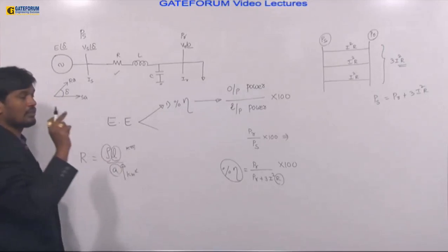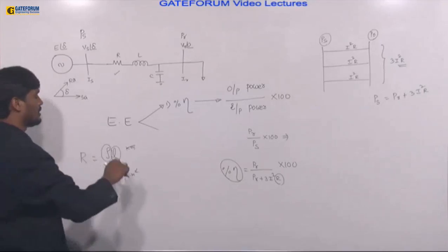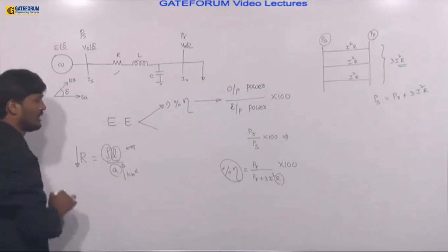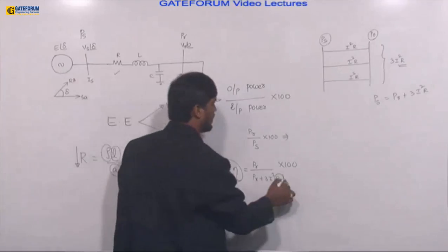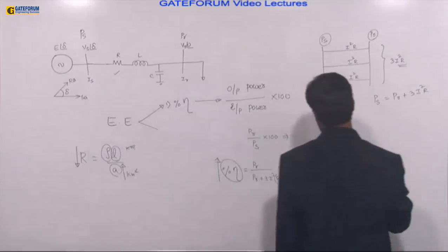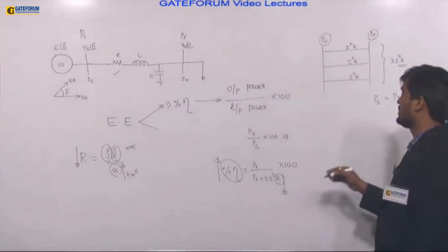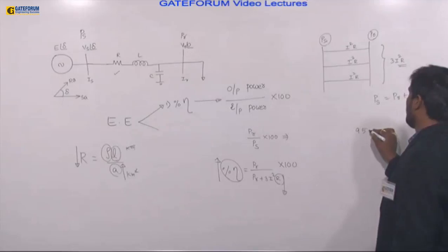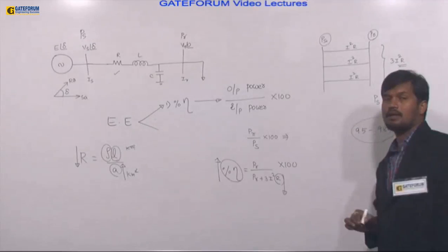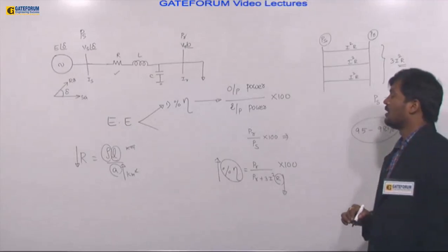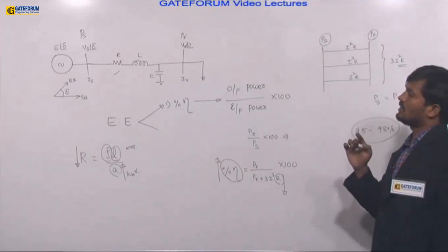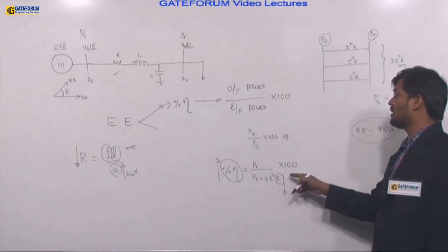In a transmission line, the conductor size is thicker. As the area of cross section of the conductor is more, what about resistance? It will become less. When resistance becomes less, what about efficiency? It becomes more. Therefore, are transmission lines operating with high efficiency or low efficiency? High efficiency. That value is 95 to 98% in practice. Now, among the three elements, which is creating loss? Resistance.